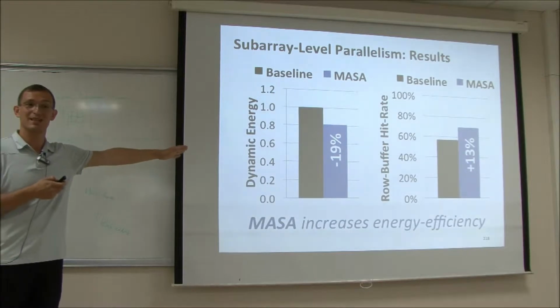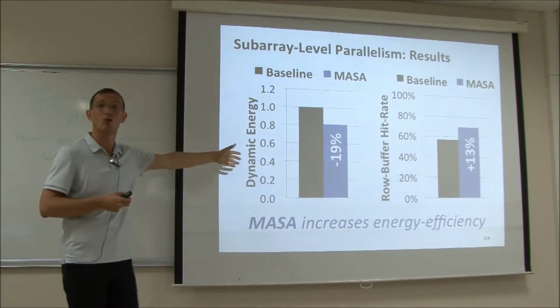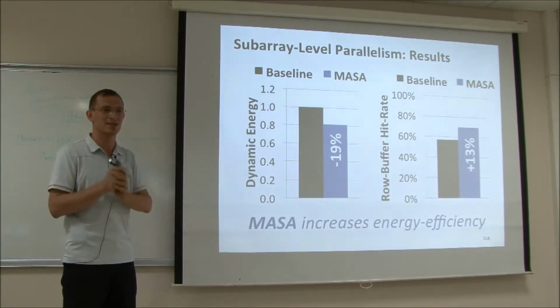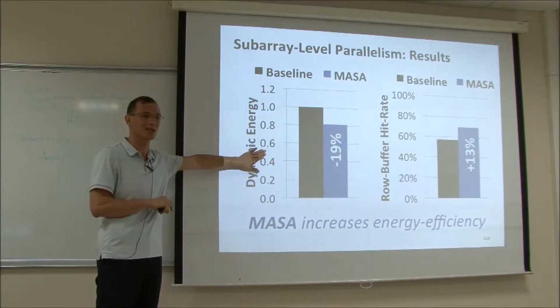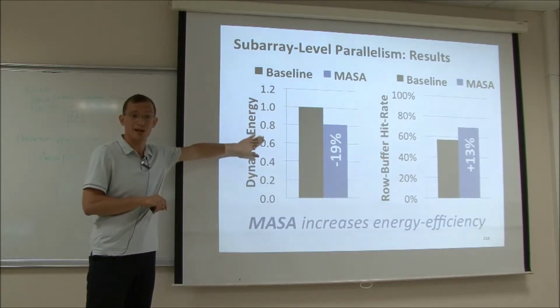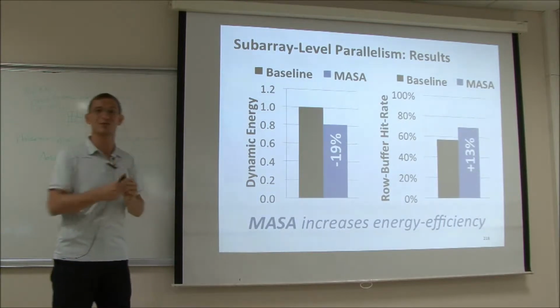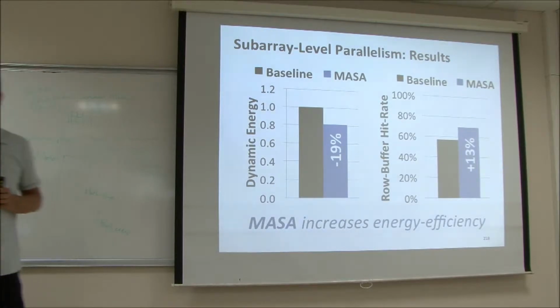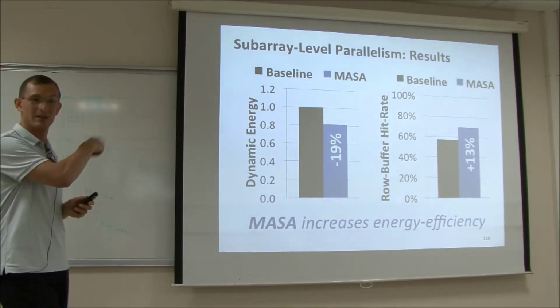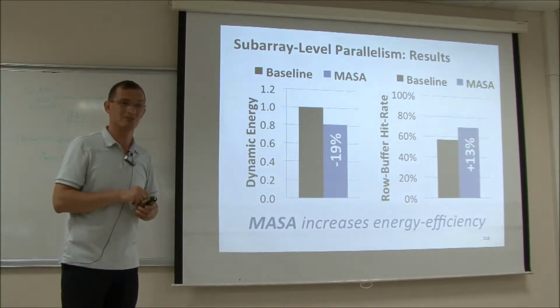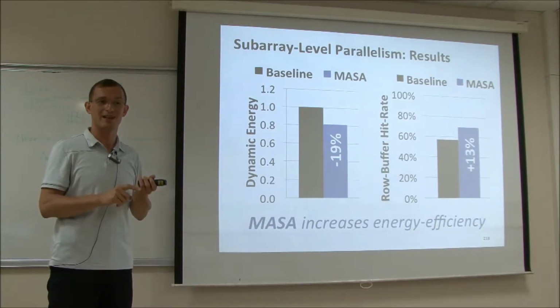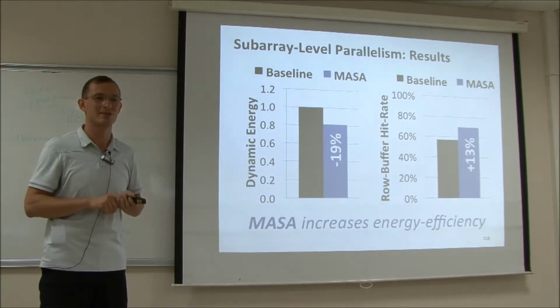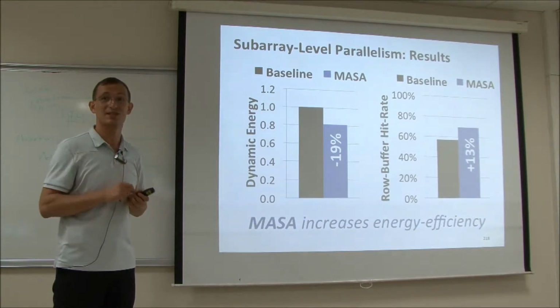In this case, we did not do any intelligent scheduling. We used the existing row hit rate based scheduling, and we looked at some application-aware scheduling mechanisms that I'll talk about in the third lecture. And it seems to work well there, but I think there's potential there if you actually do better scheduling that's subarray aware. Do you mean certain algorithms may be revisited to exploit rest of that structure, maybe? I think so. I think for both ideas that I've described, you can devise better data mapping algorithms, request scheduling algorithms to exploit the structures much better.